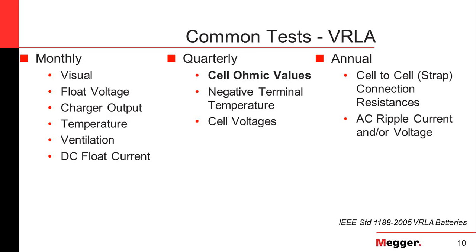However, it is stated as part of the precautions within the standard that you are to verify the voltage to ground before you begin any work. So if you follow the standard, you're still going to notice if there are any unintentional grounds by doing that test as well. Typically, these chargers are going to have some sort of ground fault indicator in them as well.